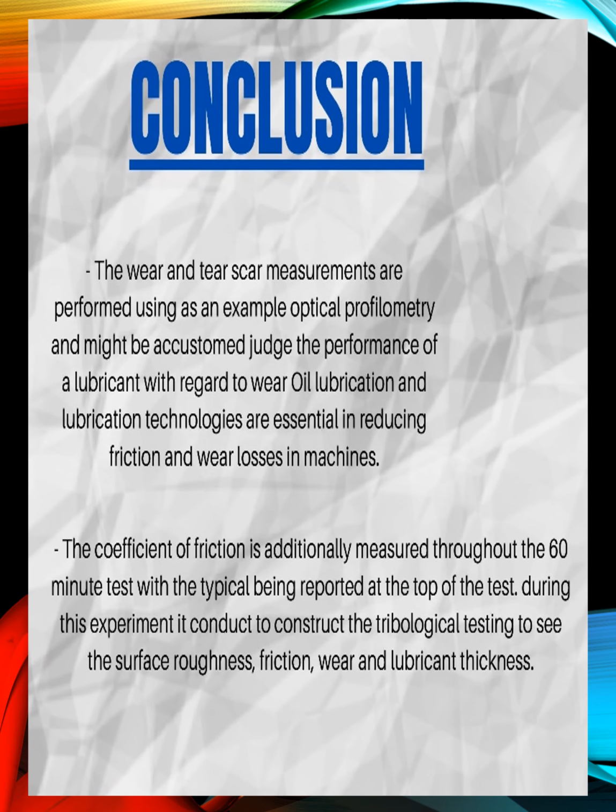In conclusion, the wear scar measurements are performed using, as an example, optical profilometry, and might help a customer judge the performance of a lubricant with regard to wear or lubrication. Lubrication technologies are essential in reducing friction and wear losses in machines.